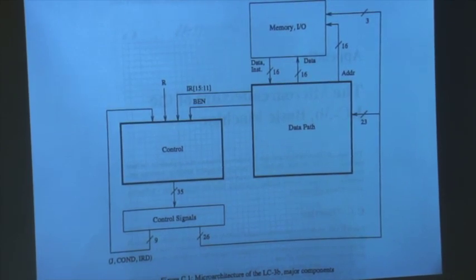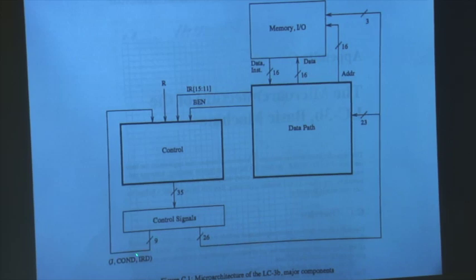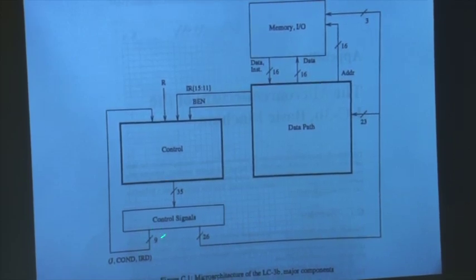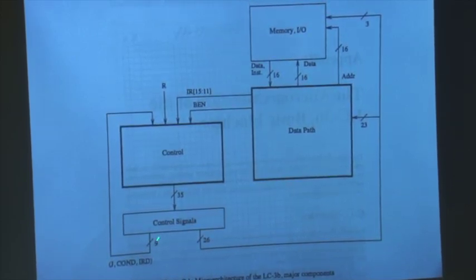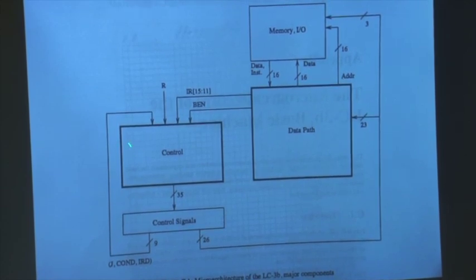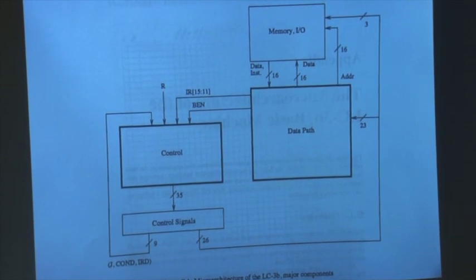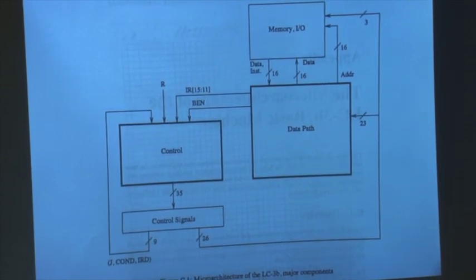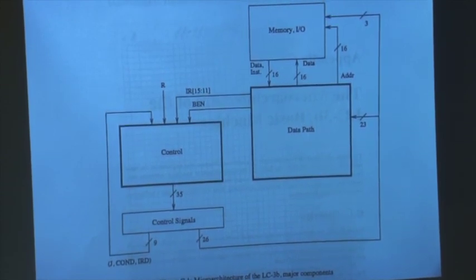They also determine the generation of control signals for the next cycle. While you're processing in the data path, you're indexing this control store. You have some combinational logic that sequences to the next state in the control store, and you're also accessing the control store to get the control signals for the next cycle.